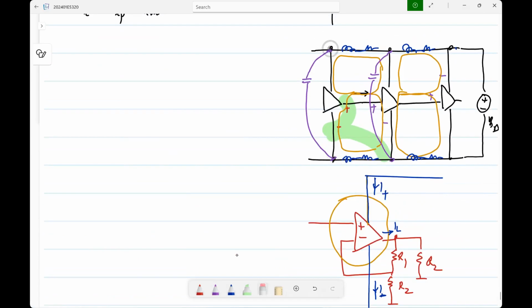Make sure that this node and that node are very close to each other in their voltages and provide return paths for current, etc. But this is a risky thing. Whenever you have single-ended signaling, you have all the voltages defined with respect to the reference node, and the return paths of the currents can be either the reference node or the upper rail. It depends on how the circuit is constructed.